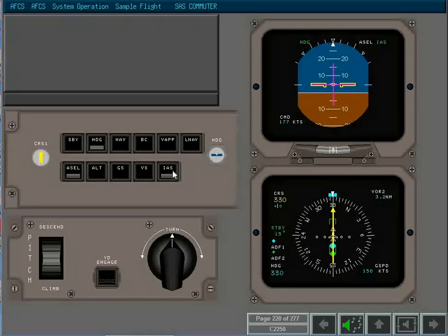As in vertical speed, power management is a pilot function. Fine-tune the speed to 180 knots. During your climb, ATC directs you to maintain heading and level due to traffic. Press the appropriate control. Alt-hold cancels the vertical speed but not the armed ACL mode. Note that AFCS captures the altitude at the moment Alt is pressed.